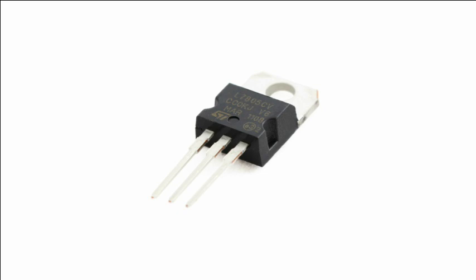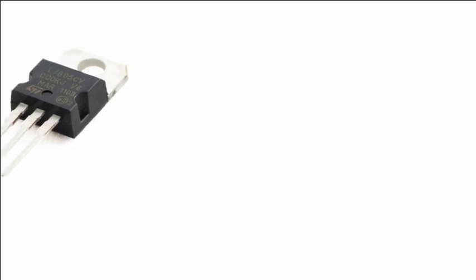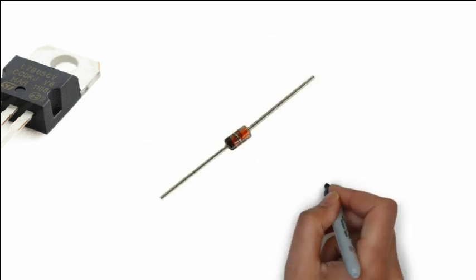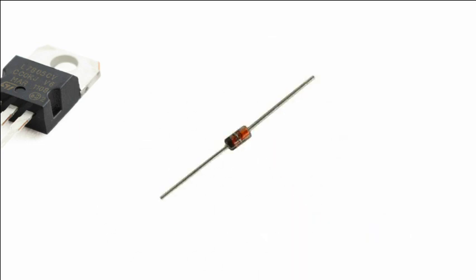It is often confused between a Zener diode and the 7805 IC. Both of them apparently regulate voltages, but their architecture and scopes are largely different. IC7805 is a series regulator formed by using several transistors, while a Zener diode is a shunt regulator which clips off the excessive voltage appearing across it.